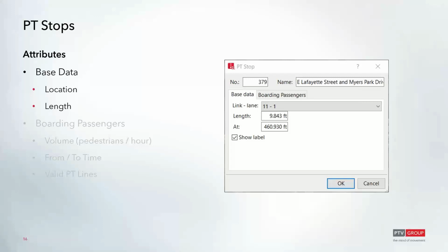And this is particularly needed, especially if you're using any VisWalk integration with pedestrians. You can also create these stops to accommodate multiple vehicles. In this case, you just want to make sure that stop, again, is long enough to cover the sum of those vehicle lengths and include some of the clearance distance between those vehicles.